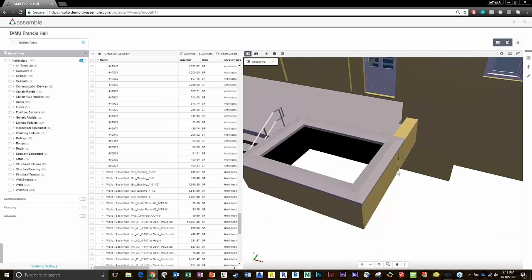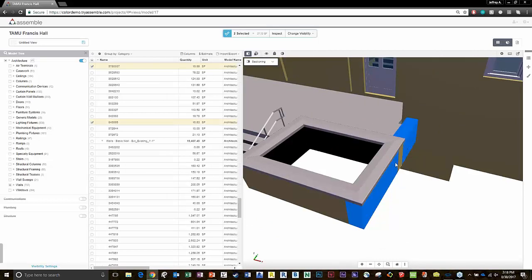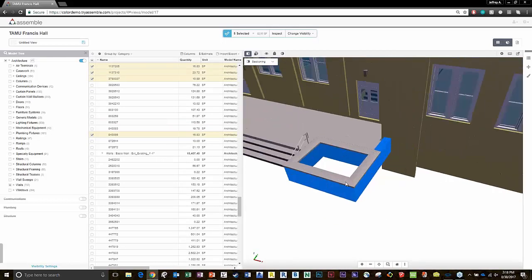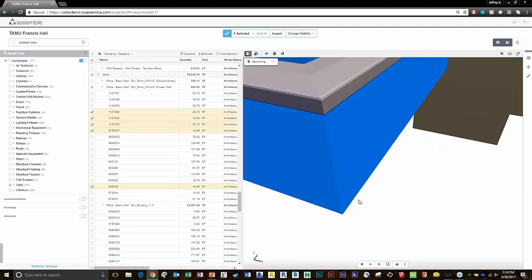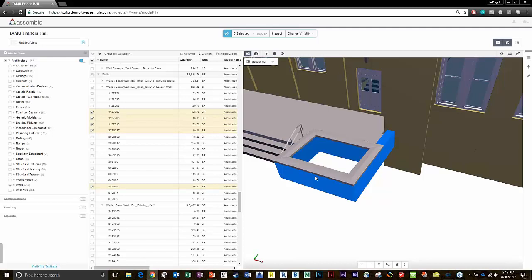that instead of going through and isolating by wall type and all these crazy conditions, if all you're doing is taking off these walls, if I just hold Control and click around, I can actually select these 5, 6 walls here. You can see they're selecting over here, but at the same time, I'm also getting a total area on the top. Now you're visually understanding what these walls are doing. By looking at this, you can see there's no foundations included. So if you know there's foundations under it, you know that it's missing. So you have that connection.